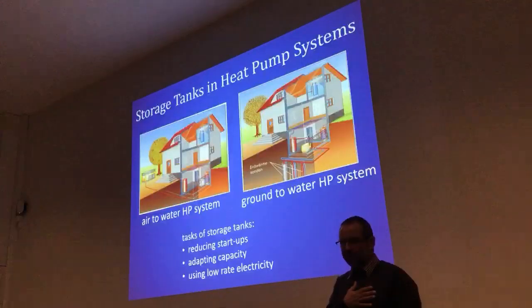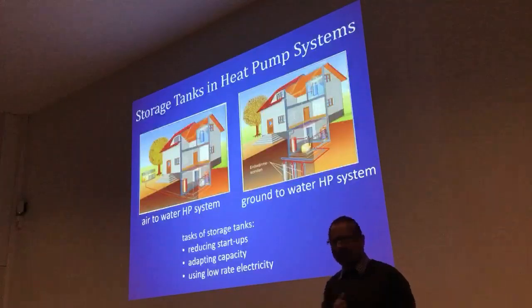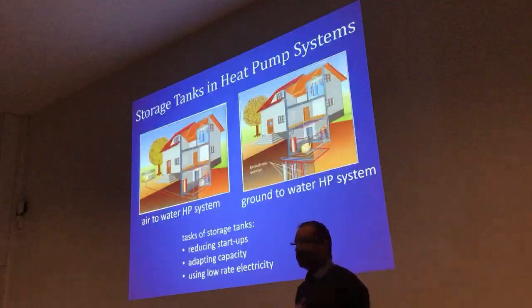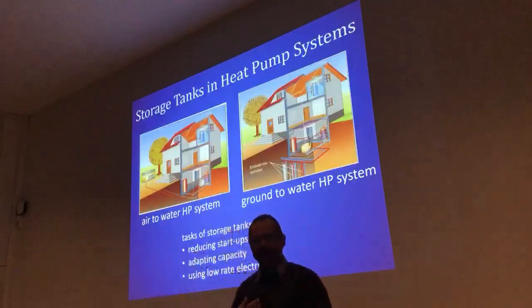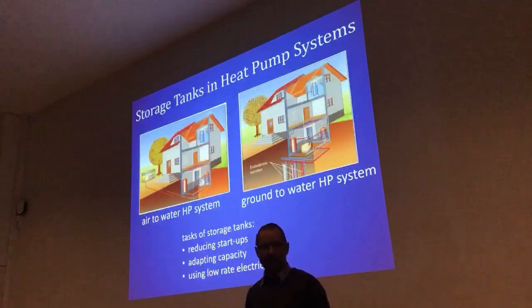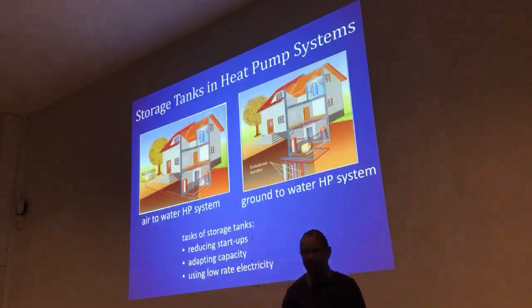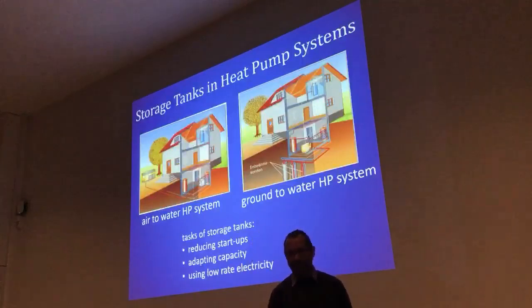We use air-to-water, ground-to-water or groundwater-to-water heat pump systems. That means we have a hydraulic water system inside the building distributing the heat to the different rooms. And in this hydraulic system, you can easily integrate a storage tank.